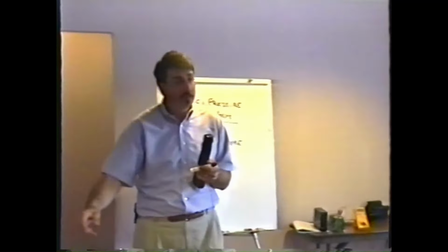Let's say we have one like this. Let's say we have one that's red, violet. Let's go nuts. Red, violet, green. All right. What's red? 2. Violet. 7. Green. 5 more zeros. 1, 2, 3, 4, 5. See, 2,700,000 ohms, right? So it is actually very simple once you've done it a few times, and we're going to have a chance to do a bunch of them here.